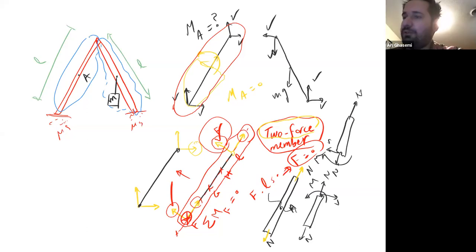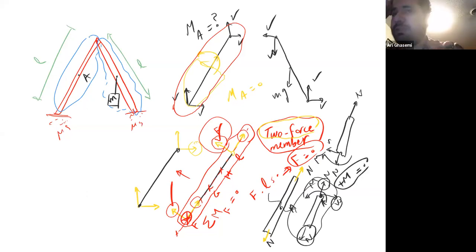If you write the equation at point A and take this system on the left, you immediately realize M plus this is 0, the moment coming from this one is 0, the moment coming from this one is 0. So only M remains in the summation of moments equation, which is equal to 0. So the internal moment is 0.